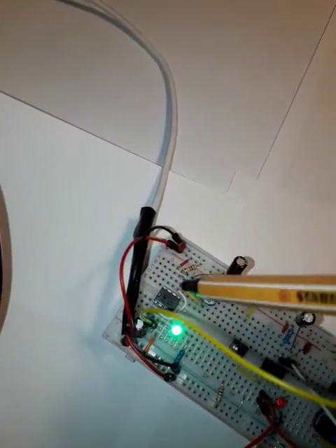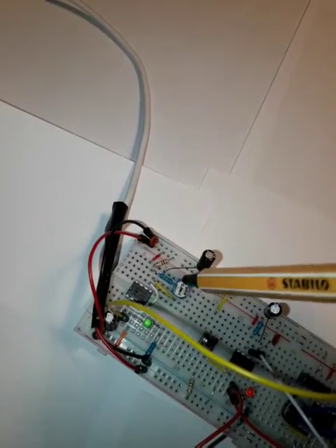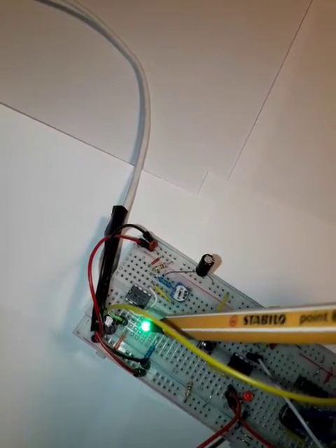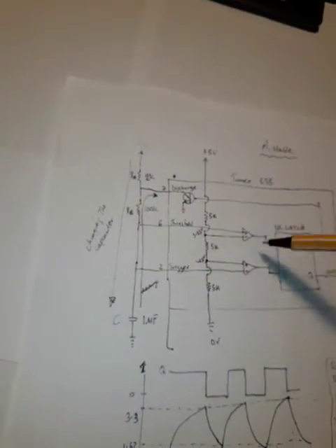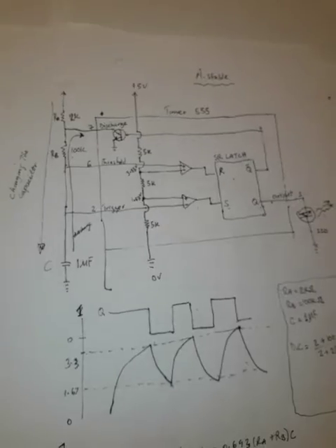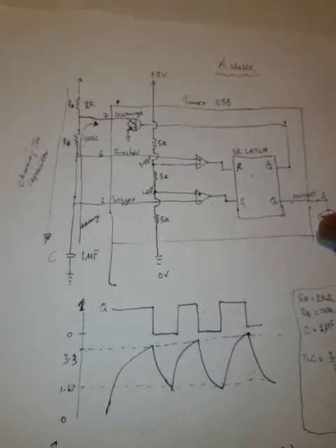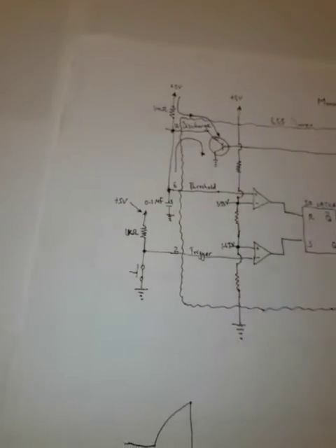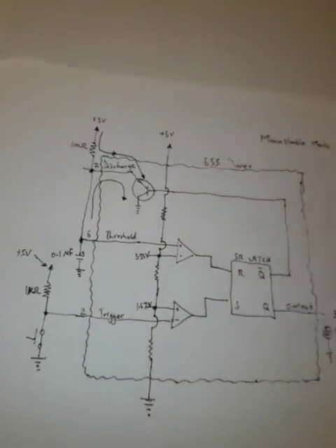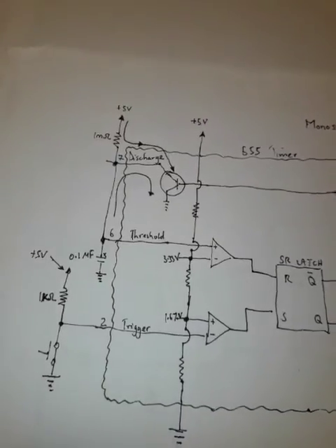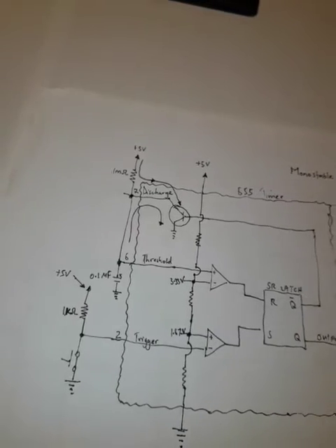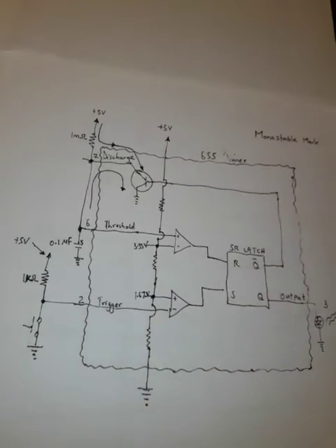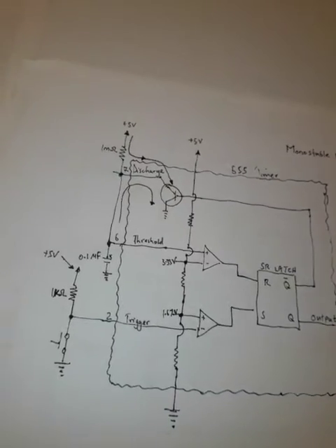I have the 555 timer, and here's my variable resistor. I can adjust the value to increase the pulse speed frequency, and this is the capacitor that is producing the input for the comparators to perform this pulse, and this is known as the astable mode. And also on the breadboard I have the monostable mode. So what this means basically is it just has one mode, it activates once and it shuts off. So we're going to see that on the oscilloscope quite shortly.